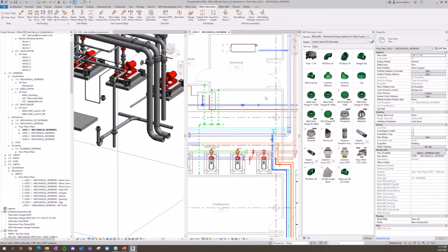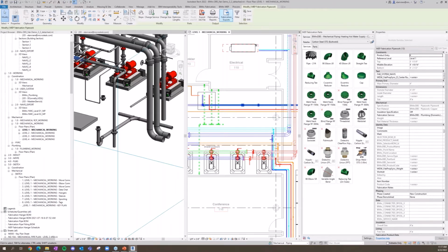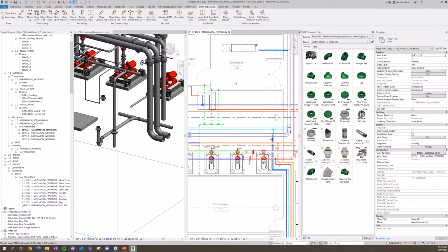This is our brand new command, heal pipe. It allows me to grab those sections that I want to be a single pipe, go back to fabrication and ask it to heal those pipes for me. It generates it back as that individual pipe, which I can then optimize later based on whatever changes and settings I've dealt with. Very, very nifty tool. Makes fabrication even easier to handle.